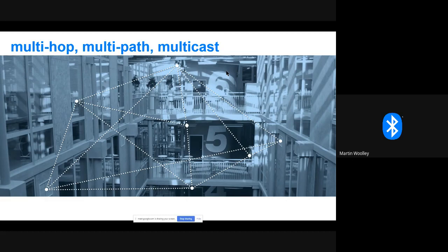Almost all of the communication that devices do in a Bluetooth mesh network is of the multicast type. In other words, a single message addresses and is ultimately delivered to more than one device. The whole system is designed around multicast communication, as opposed to having to do a whole sequence of unicast communication, talking to a collection of individual devices one at a time. You send one message, and the way the addressing and message delivery scheme works, that's all it takes to get to all of the appropriate devices that need to receive that message.